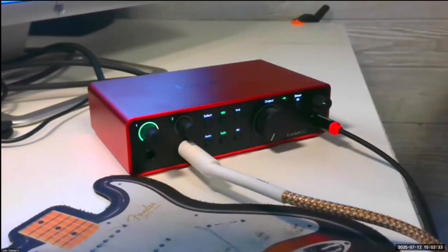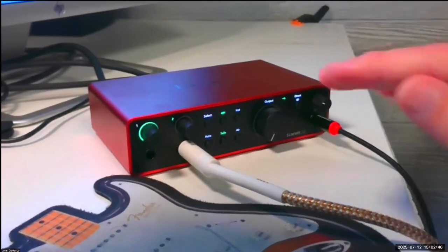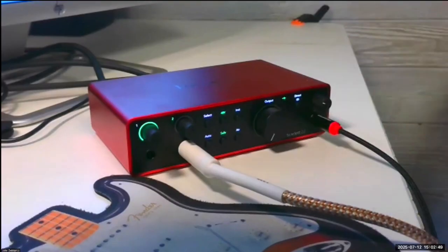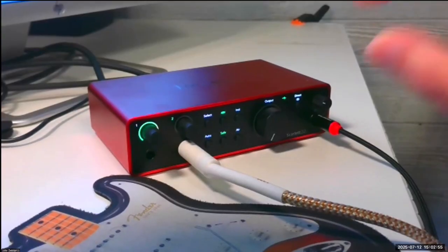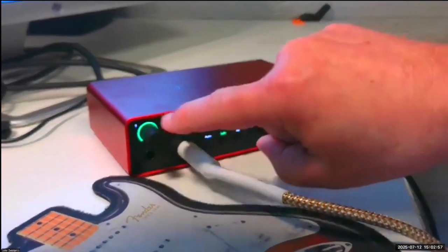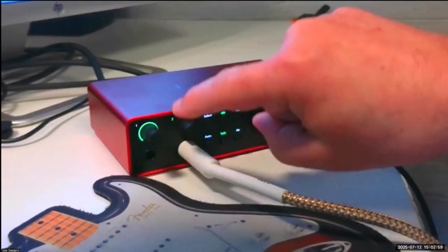And this particular model, and Michael's, you can do a thing called auto gain. And I'm not going to teach you that. I'm going to teach you the old-fashioned way of doing this, which is you plug your guitar in, or your microphone, and then you start testing, and you set your level by looking at whatever your feedback is, for you don't want to clip.